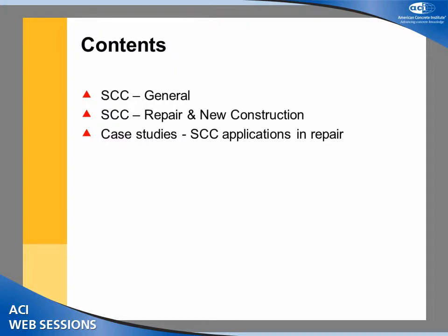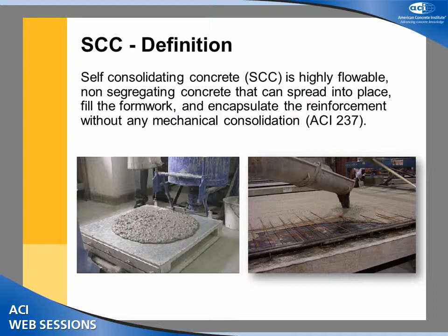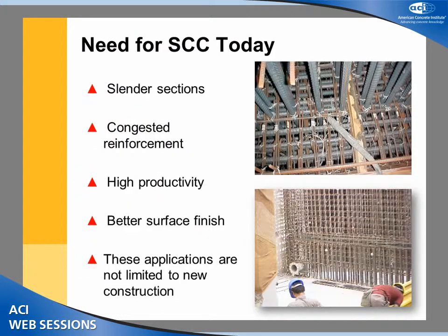The contents of my presentation today are going to be talking about SCC in general, the difference between SCC in repair and new construction, and we'll briefly go over 6-7 projects, a lot of pictures, on SCC applications and repair. SCC in general, just to whet our appetite. SCC is a highly flowable, non-segregating concrete that can spread into places, fill the formwork, and encapsulate the reinforcement without any mechanical consolidation. This is the definition by ACI 237.